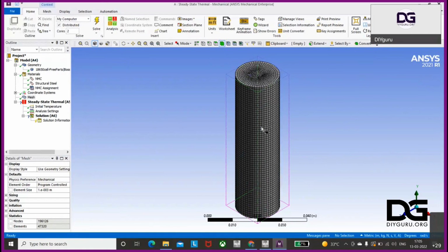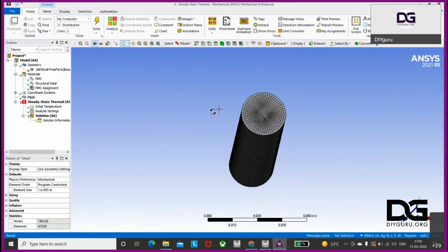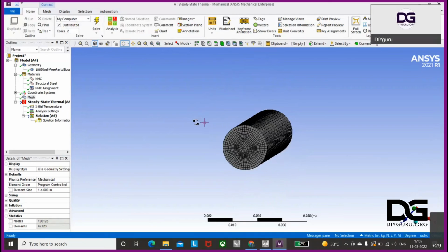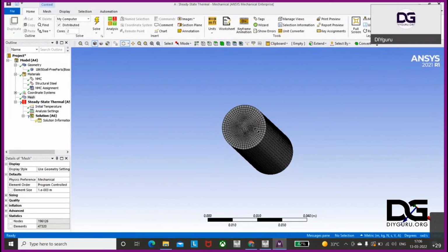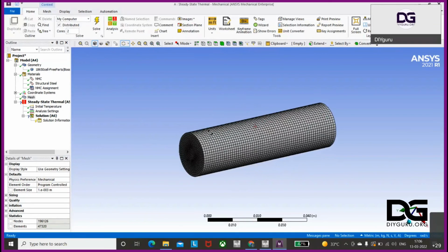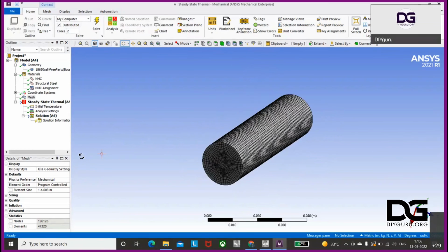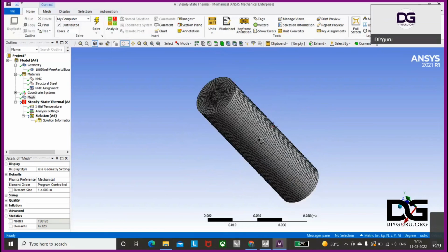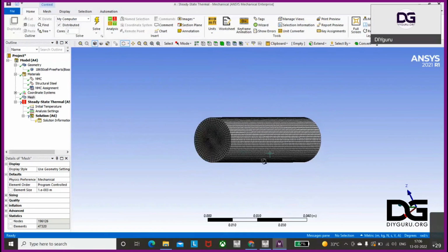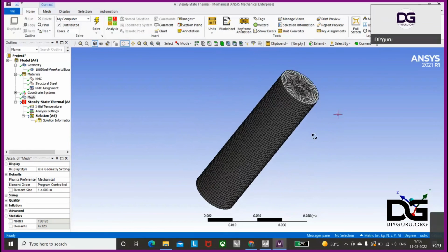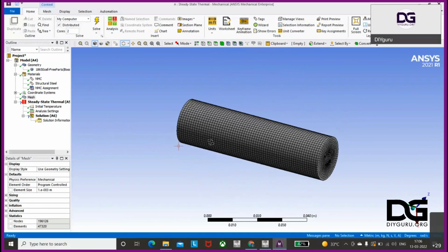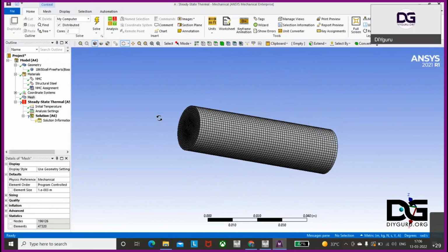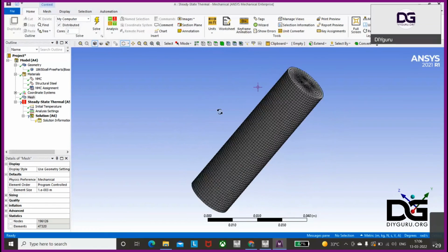Okay, and you can see how many small elements my whole geometry is divided into. But this is not very proper meshing. Okay, there are very skewed elements over here. Okay, but if I take time to rectify it, it will take the whole session right now, and I have to show you further things as well. Okay, this is automatic mode I've taken. You have different types as well. Like if you want to make a clear mesh and everything, you have different modes you can use.